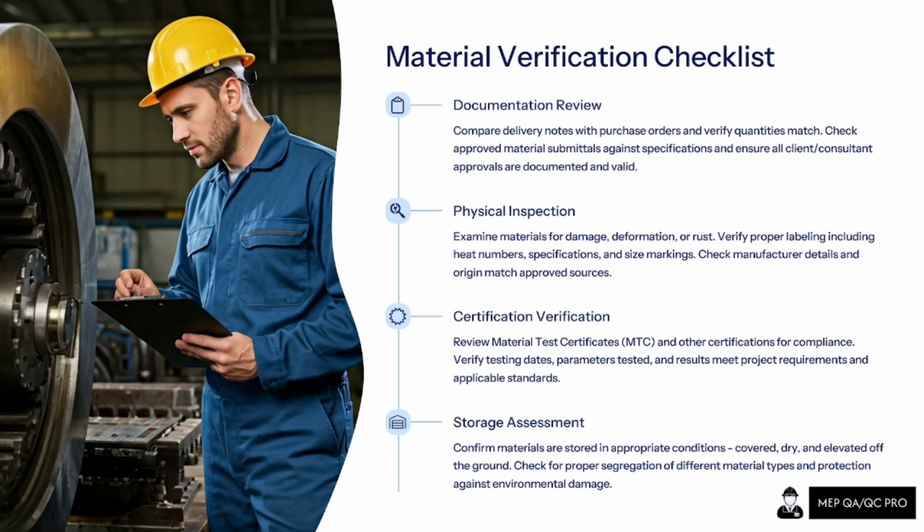You will start from document review. You will see the purchase order. You will verify the quantity which is delivered. You will check against the project specification, and you will ensure that all the documents are approved by the consultant.